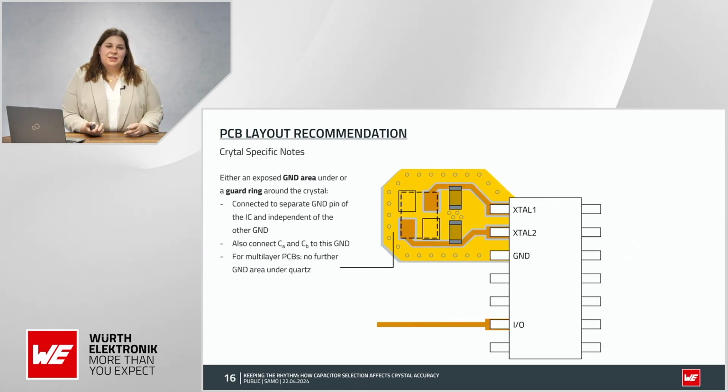What are other PCB recommendations for crystals specifically? You should have an exposed ground area or a guard ring around the crystal. This ground area should be connected to a separate ground pin only for the crystal circuit, because if it's connected to other ground areas, it could be interfered with by signals that are on there.